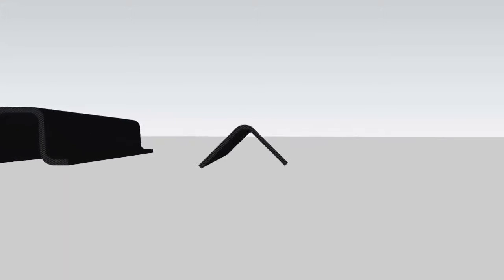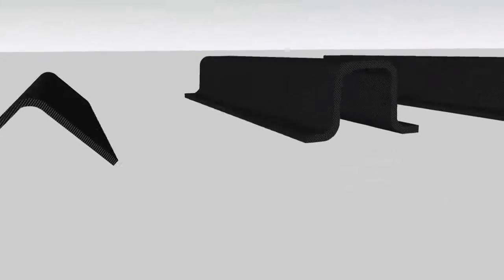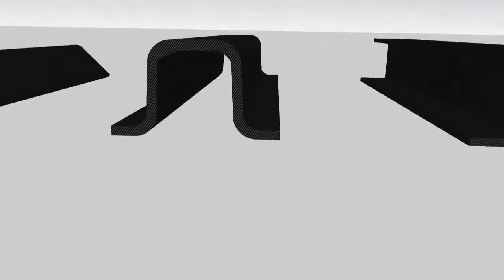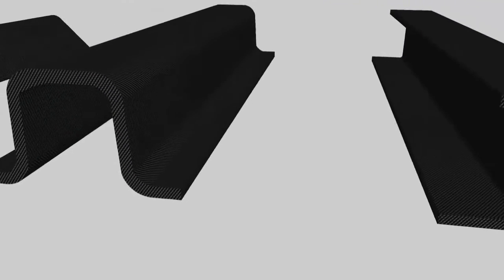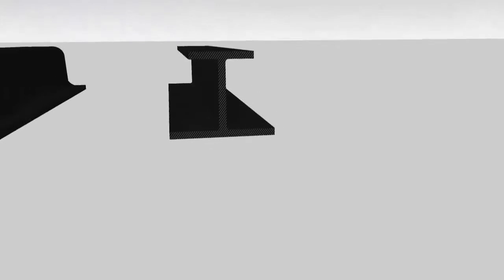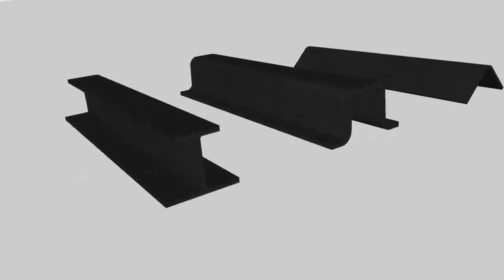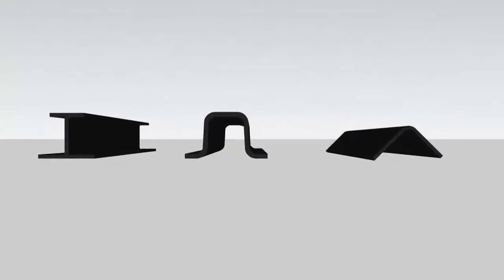The structures to inspect include the fuselage and different parts of the wings, the skin, stringers, and spars. All these components have different shapes, mostly quite complex, so the examination method must be able to adapt to those challenging conditions. The manufacturing process of composite materials can generate different types of defects, porosities, foreign bodies, and delaminations.